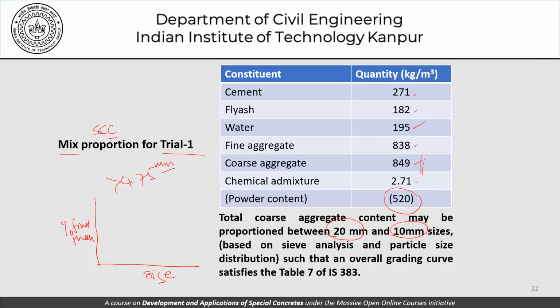Finally, there will be a size here which will correspond to a value 100% is finer than this value. Also, there will be a size here where you will find nothing is finer than this value. So for every size we need to have a certain value for percentage finer than, and these values are often given to us in a code by way of a distribution.